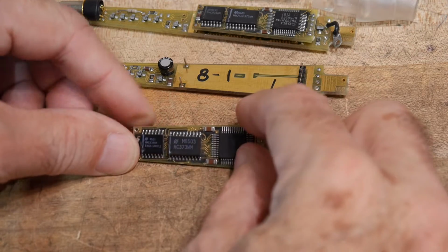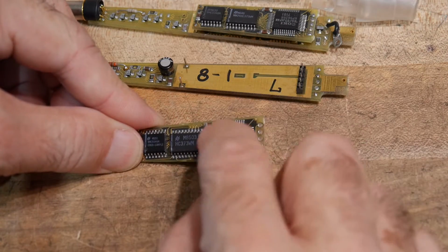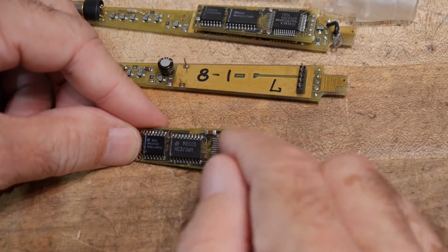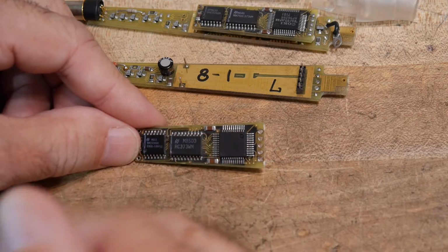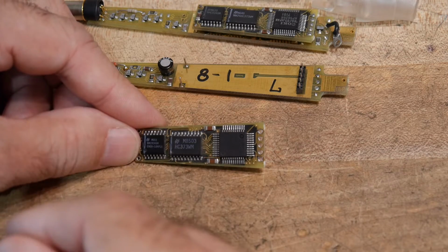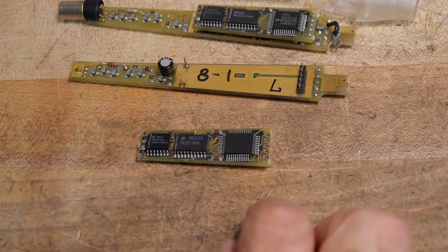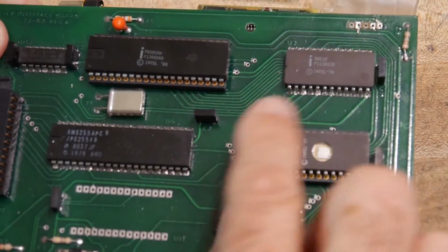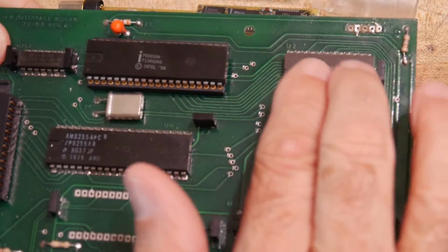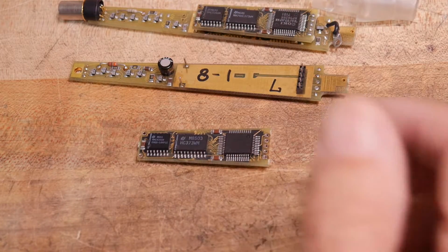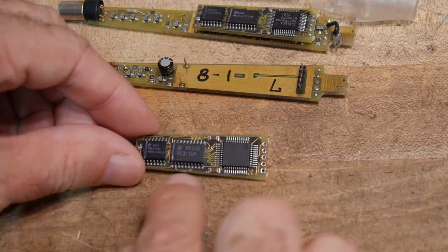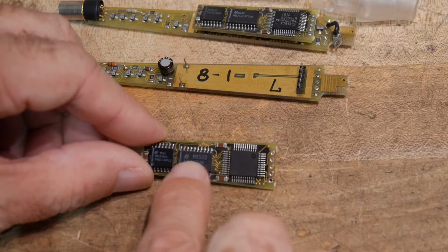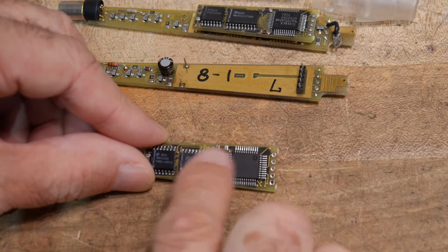So on the top here is an Intel 8051, or a version of it. Remember that the 80 series of microprocessors from Intel always required a demultiplexing of the address. Remember on like 8085 boards, there's always a chip that does the demultiplexing of the address lines, and sometimes it's a 573, which is a particular part. Here we have a 373, so this is doing the demultiplexing of the address line, so that's required.